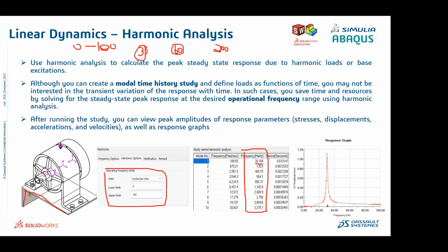You can see the stresses or amplitude displacement peak at this location, right? So wherever your natural frequency is, basically this 30 hertz is my resonating frequency. At this resonating frequency, you will understand, yes, this is my resonating frequency. From the software point of view, you can evaluate what the maximum stresses and displacements are, and whether my model is failing during the dynamic event.